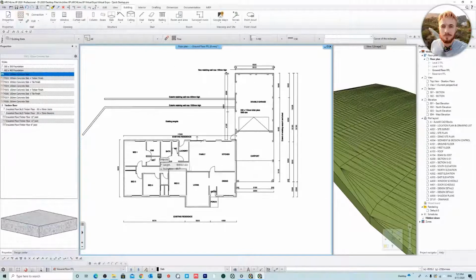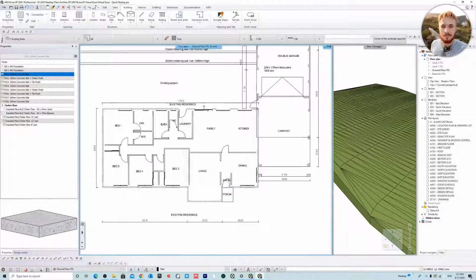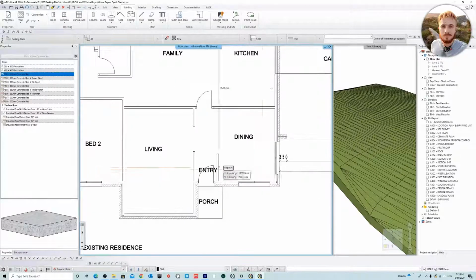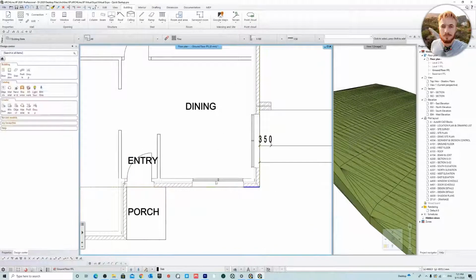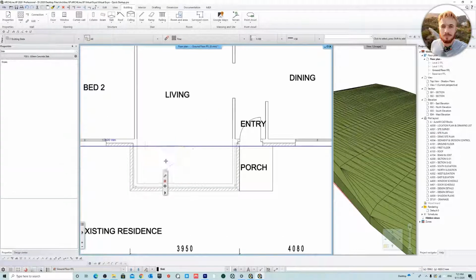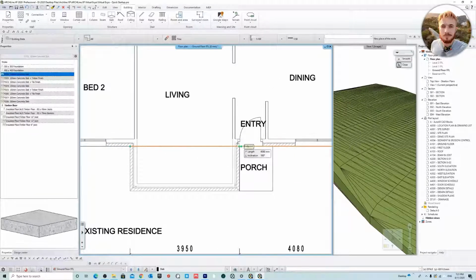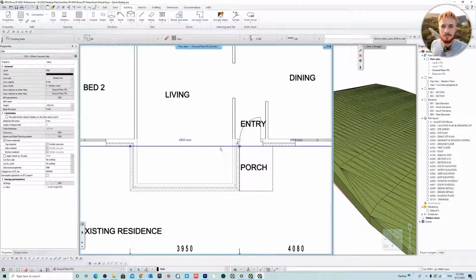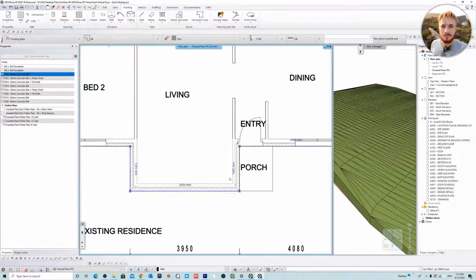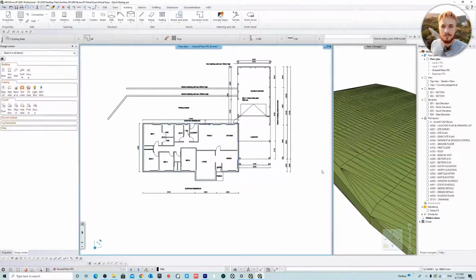And for this one, I'm just going to select just a rectangle because I want to see how this slab is going to interact with the terrain. So I'll select it like that. And I'm also going to go insert node like that and insert node like that, which is simply just clicking on the line and you can see this menu pop up. So I'll offset this. Okay, so now we've got a slab.